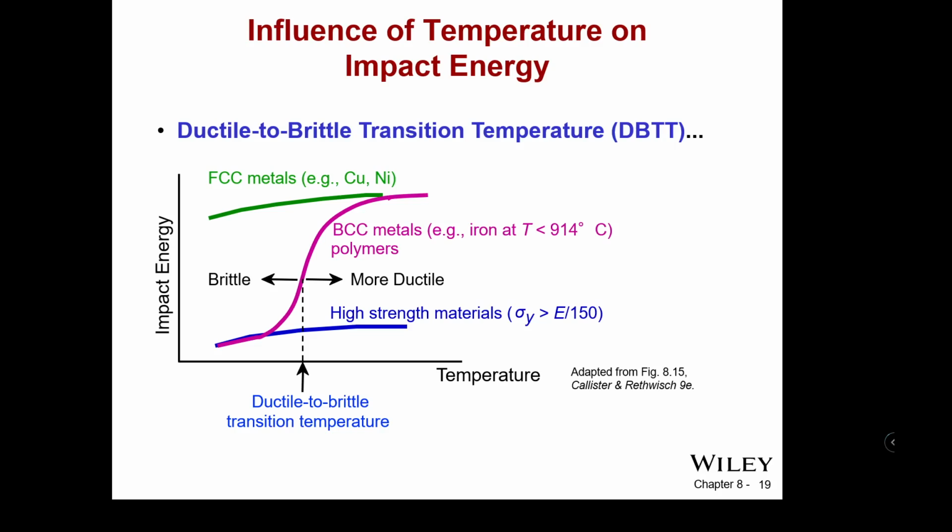Irons and things of that nature, a lot of the steel materials, have to be fairly low temperature, and the way that we get there in that particular lab is by way of some dry ice to be able to cool it sufficiently to get it closer to that more brittle state.